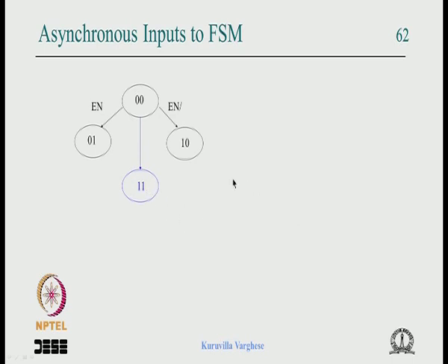Again the solution is that never branch on asynchronous input like this, like when it is 1 go to some state and 0 goes to another state. You should always adopt a go no go structure. When it is 1 transit, when it is 0 remain there, and this should be grey coded.